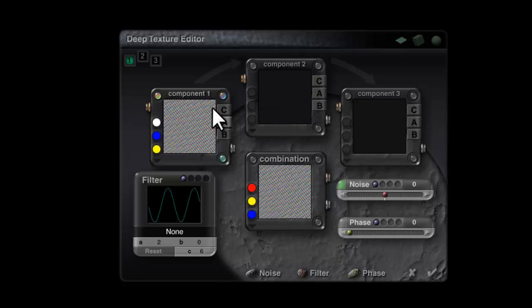And the result of that is this output, which you can't display properly, but you'll see that it's got these sort of different coloured diagonal lines, is very negative. Far more negative than you would normally be capable of having an output. Now we need to make this a positive output. We need to bring it down a bit because it's got to come into a range where it's useful, and if we just make it positive, it'll be so far out of range we won't be able to use any of the controls in the Material Lab to bring it back under control. So we have to do a bit of the work here.